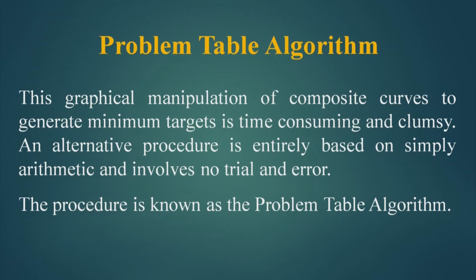However, if the number of hot streams and cold streams is very high, then using such a graphical method is cumbersome. Further, this method has to be operated by a computer, and thus an alternative procedure is suggested, which is based on simple arithmetic and involves no trial and error.